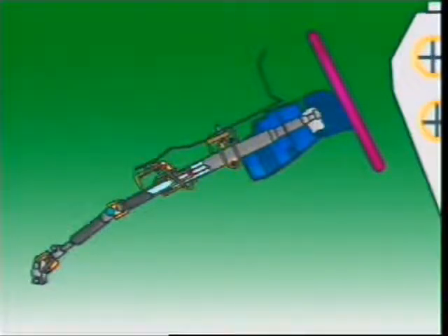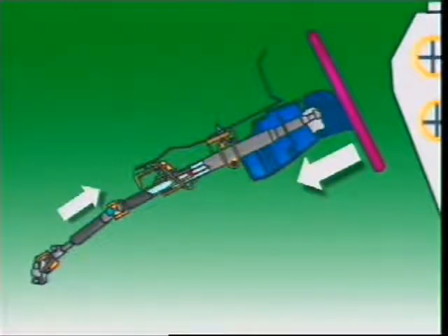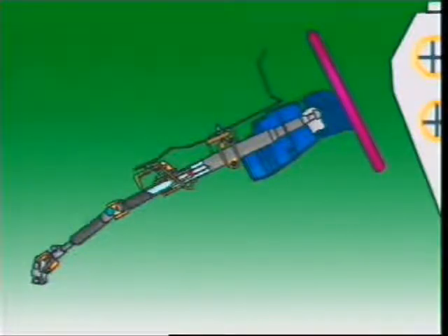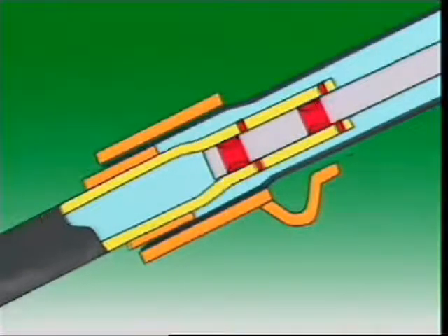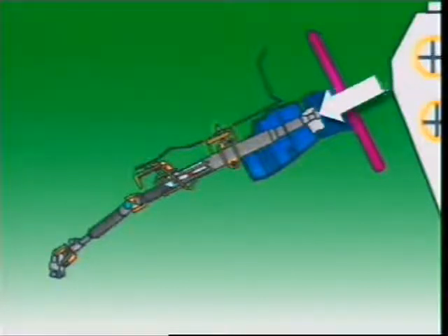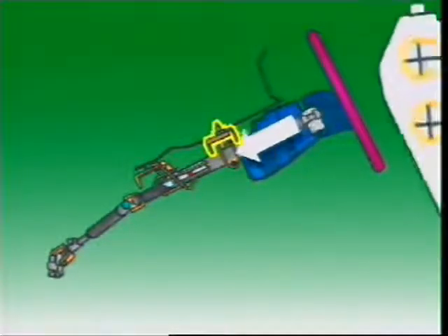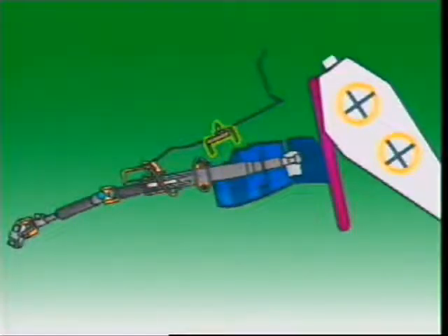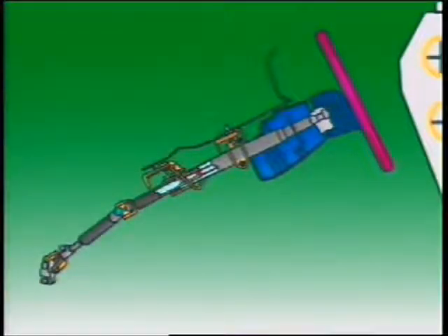During a collision, two forces are applied to the steering column. The first is the force of the steering box being forced back towards the steering column and towards the driver. Plastic shear pins allow the lower shaft to move over the upper shaft. The second force is the mass of the driver striking the steering wheel. This force breaks the brackets on the upper part of the column, driving the upper column into the lower column. The steering column is connected to the input shaft of the steering gear by a flexible joint. This allows for alignment and reduces the transmission of road shocks back to the driver.